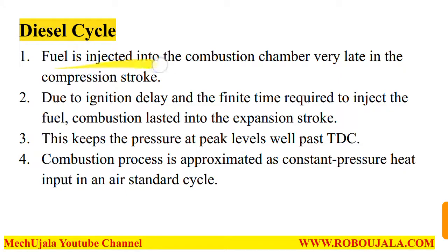So fuel is injected into the combustion chamber very late in the compression stroke. Due to the ignition delay and the finite time required to inject the fuel, combustion lasts into the expansion stroke, and this keeps the pressure at peak level well past top dead center. And the combustion process is approximated as constant pressure heat input in an air standard cycle.